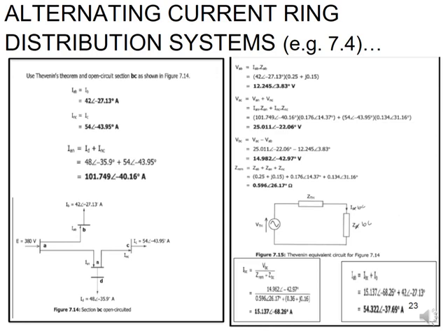Then I can work out what my IA was going to be, IAN. Now that we've got the different currents, I can then work out what my VAB is, and I can work out what my VAC is, simply being my VAN plus my VNC. Then what would VBC, your open circuit portion, be?